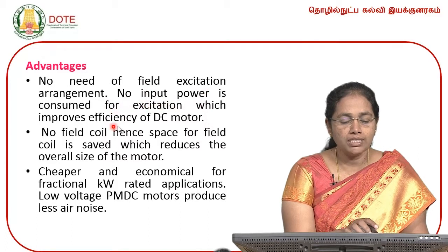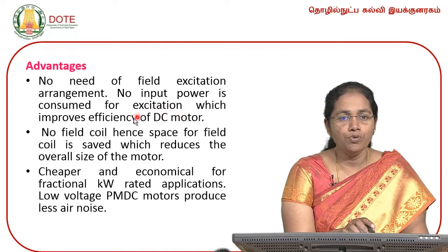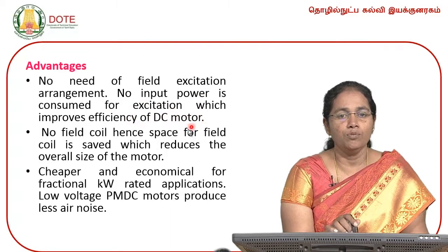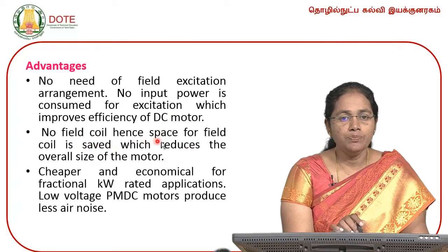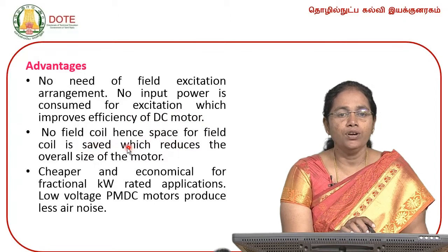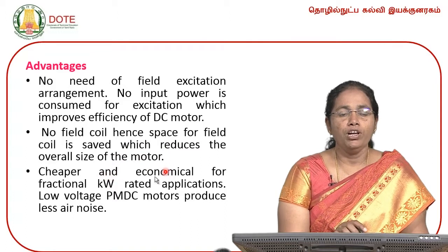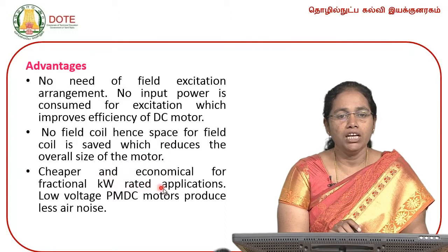No input power is consumed for excitation, which improves the efficiency of this DC motor. No field coil, hence space for the field coil is saved, which reduces the overall size of the motor, and this is cheaper and economical for fractional kilowatt rated applications.